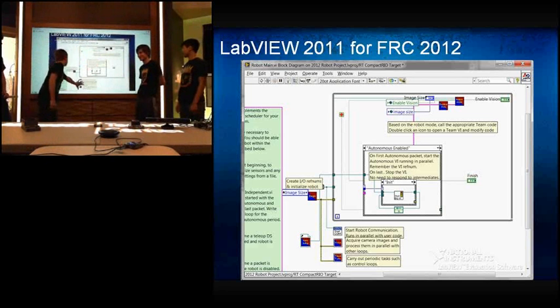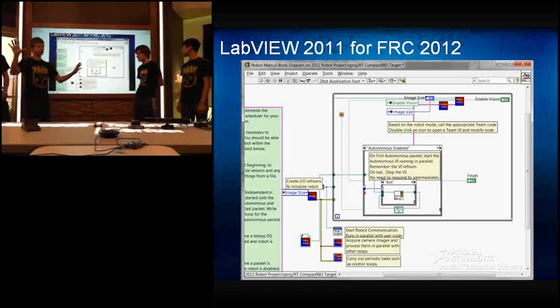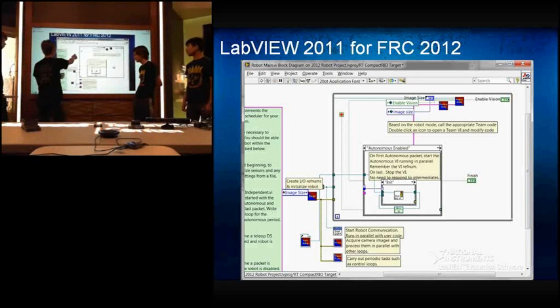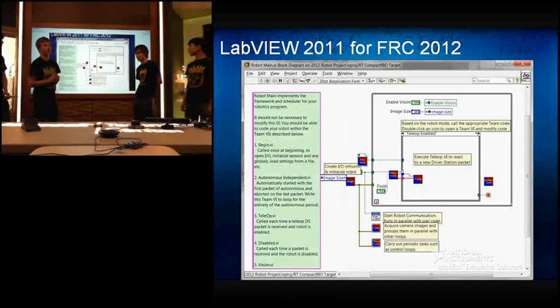It would move these things around, it would move that box around, and really, any modules or areas you had set up, let's say drive up here, arm code down here, and sensors over here, is just going to be totally thrown into whack. And they're just going to be merged into one. Now, if you select an area and click the cleanup button, what you'll get is just that area is modified, which is really nice because that lets you clean up each individual module while leaving the bigger picture alone.